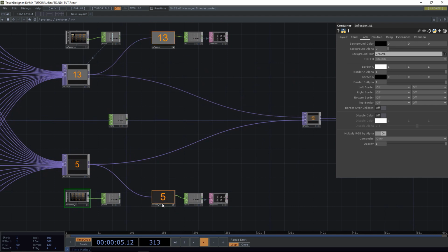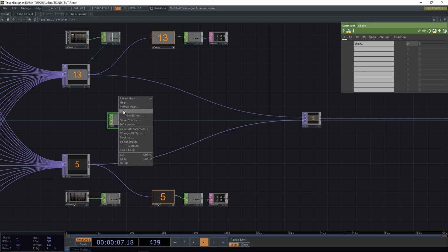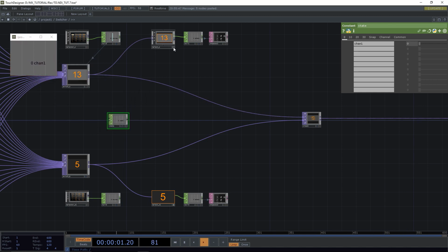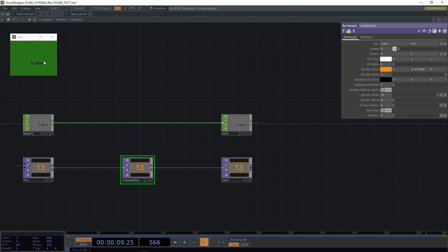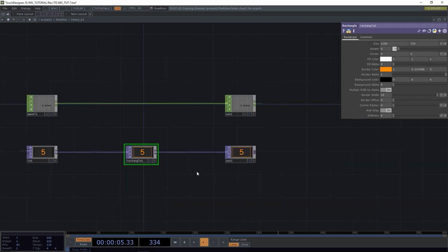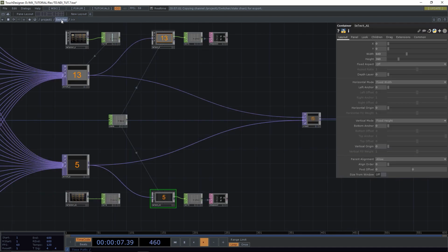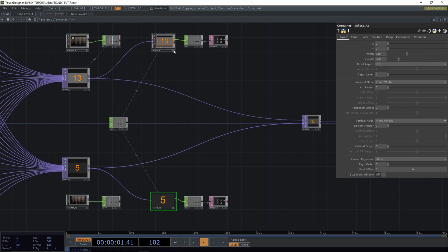So now these switch state. And what we want to do now is to make state switch the orange frame. So I'm gonna go to state here, dive in there, and basically, if state is 0, this has to be visible. So let's take this to the border alpha. Say 1 minus state. It means when state is 0, it is visible. Let's copy this. Let's go to the other side. Paste this. Put here without the 1 minus. So this one becomes 1. It's 0. So let's just see if that does what we want.